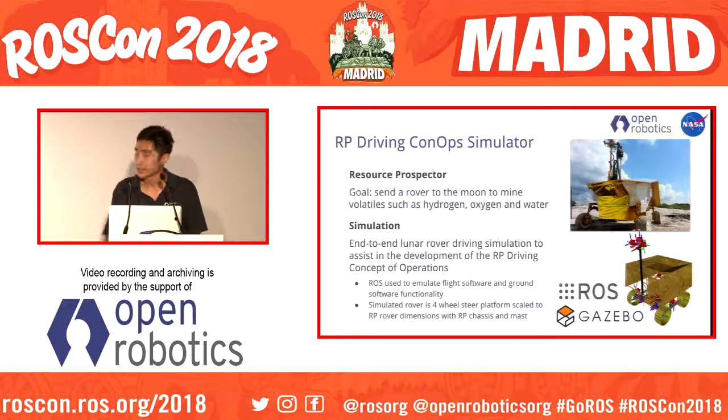In the image you see on the right, that's a prototype RP-1A. It's built on top of the KREX mobile platform. It's got active suspension. Each wheel can be controlled individually, and it's got hazard cameras all around the mobile platform, looking at its wheels in case it gets stuck. There's also another camera looking out the back. And on top of the rover, there's a mast that carries a stereo camera pair mounted on a pan-tilt platform, so you can look around while the rover is being driven.